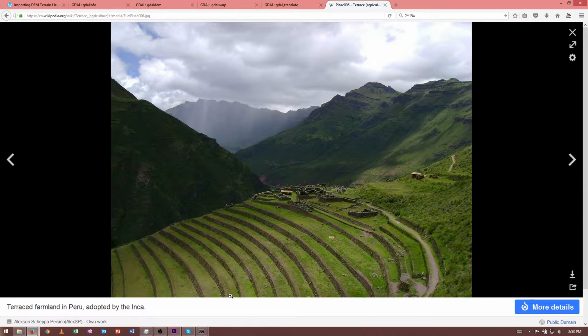So we can get around that by using 16-bit height maps, and because we basically have 65,536 different unique levels, the resolution, or the difference between each level, ends up being about 2 centimeters in this case, which hopefully you can see how that would avoid this sort of staircase effect. So how do we go about converting our TIFF DEM to a normalized raw?